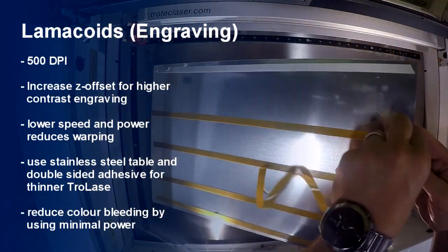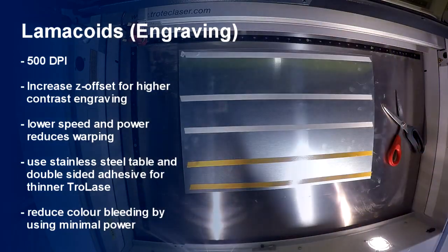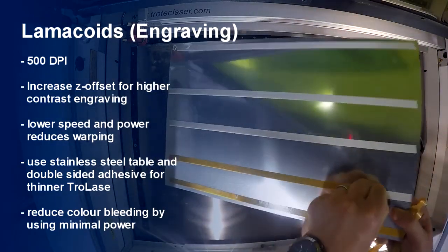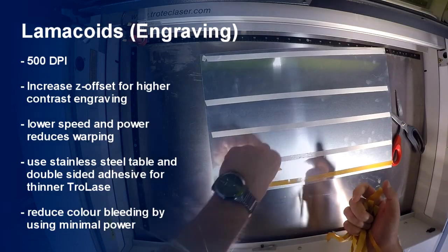Use minimum power to remove the top layer of any 2-ply Lamacoids. Engraving too deep would create excessive residue and color bleeding.